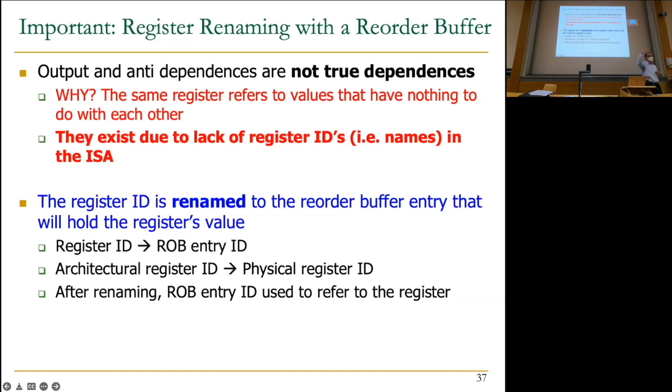It's not tied to the instruction set architecture. Internally, you can make the machine extremely big. But instruction set architecture is decoupled from the microarchitecture right now. So there are a lot of really interesting things that happen with register renaming. You're basically freeing the design from an architectural constraint. You're making it microarchitectural now with the rename.